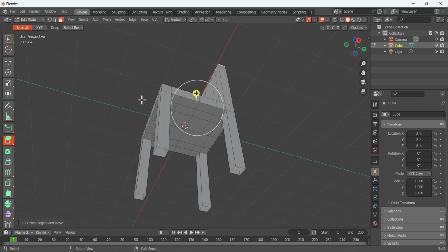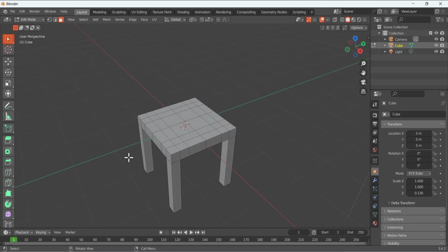Okay, now by mistake we already selected these faces. So to undo this step, go here on the edit and undo it. So now you can see by mistake these were already selected. So we have to press here, selection, press here, so we deselect these ones, and again go here, press the shift, select these faces.